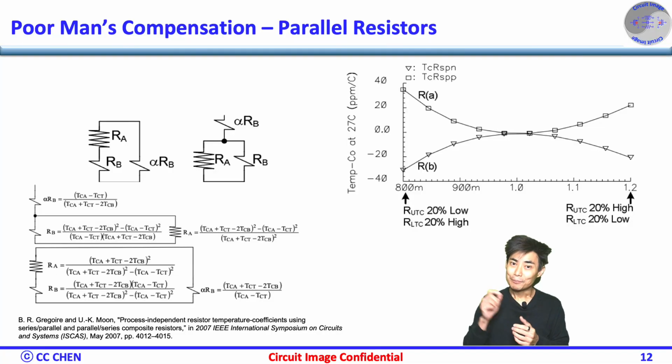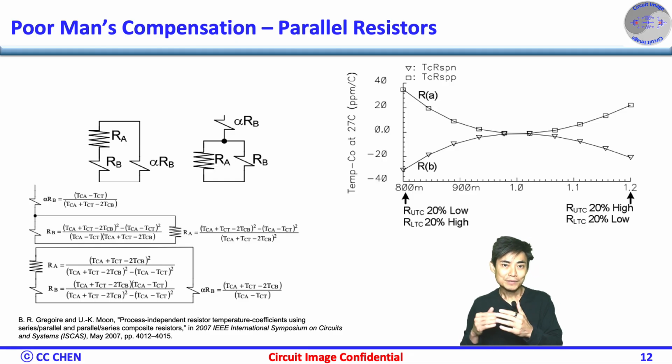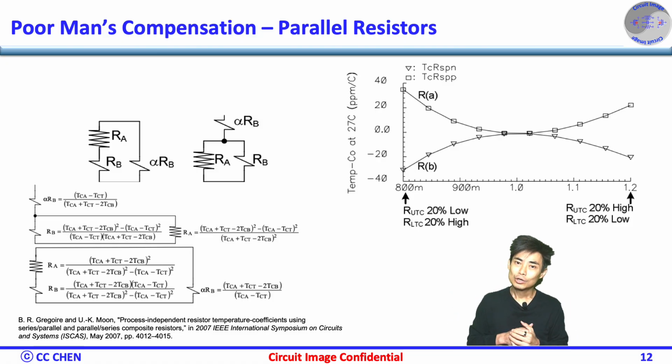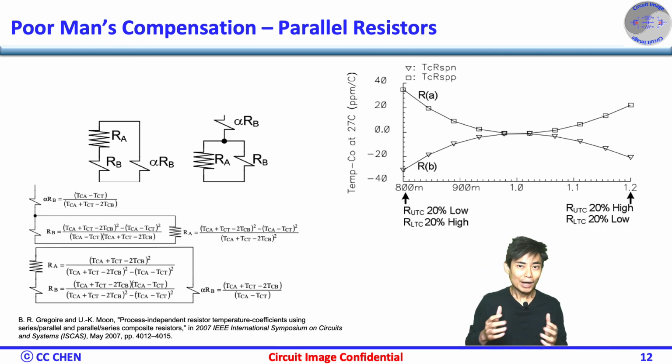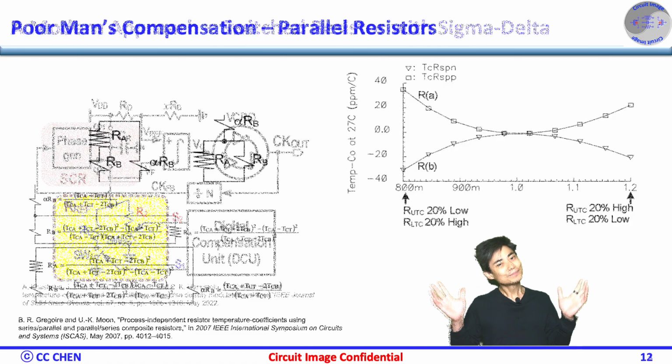Right, a basic way: combine two resistors with opposite temperature coefficients in pair. Adjust their ratio so that drifts cancel out. This method works, but the tuning is costly. You will also face challenges like resistor spread and switch parasitics. What else could we improve?